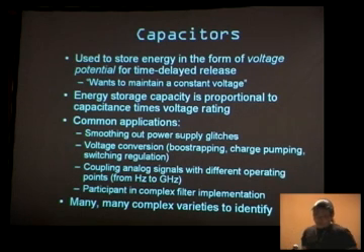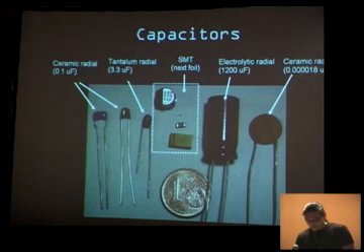If you lose a couple, it usually doesn't hurt you too much. They're also used for voltage conversion, bootstrapping, charge pumping, switch regulation, coupling analog signals with different frequency operating points from hertz to gigahertz, and they participate in a lot of complex filter implementations. So there's a lot of varieties of capacitors out there. In fact, I'm kind of a capacitor connoisseur.